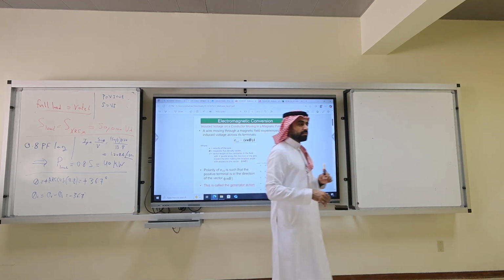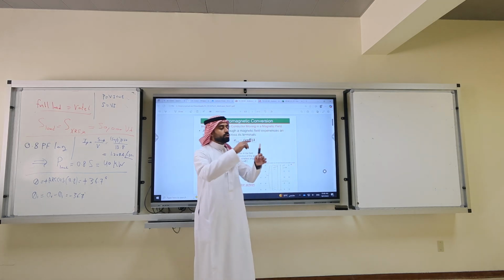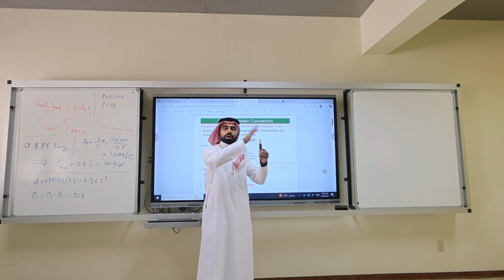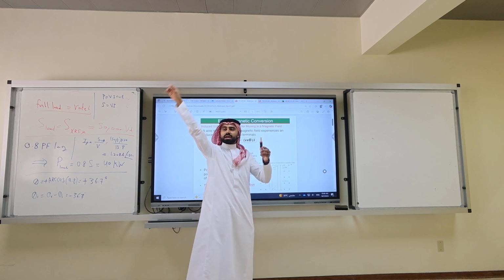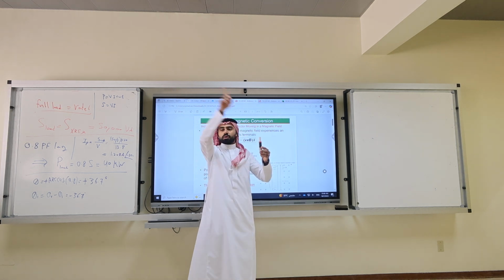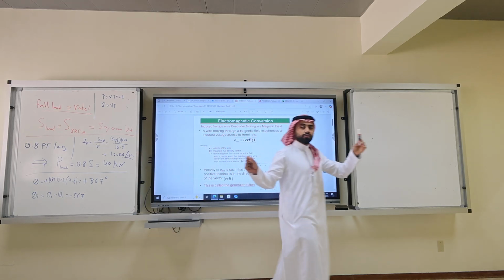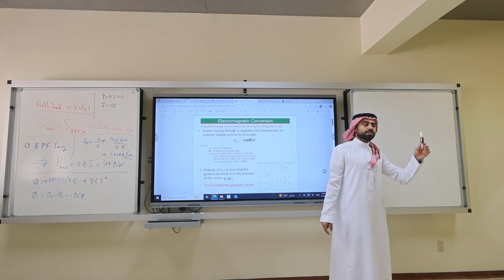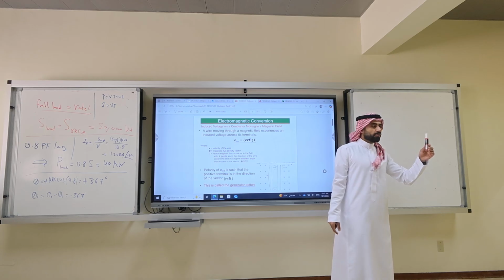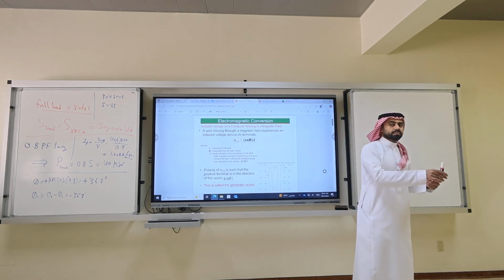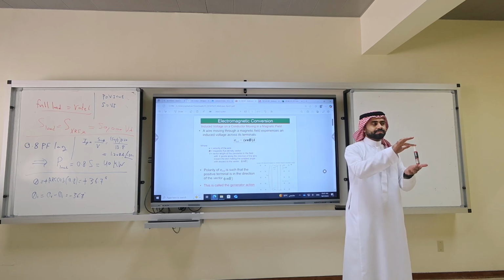Physics 102 says an induced voltage, with plus and minus, will appear on this coil. If I close the circuit, current will flow. While I'm moving it, current will flow. The moment I stop, current will not flow. The voltage will disappear. So as long as I'm moving, induced voltage will appear.